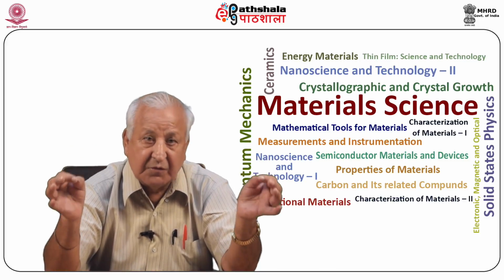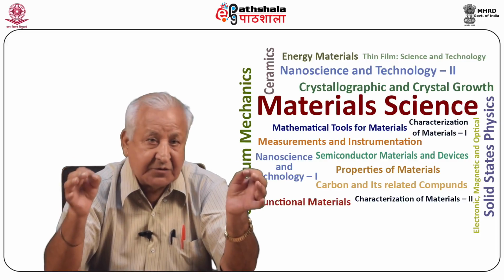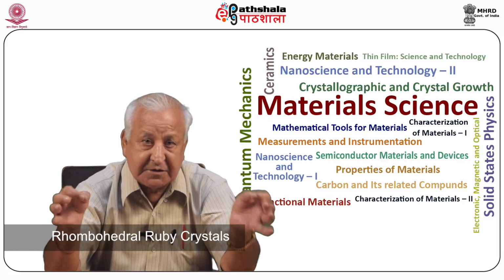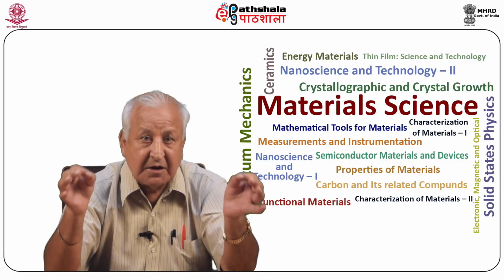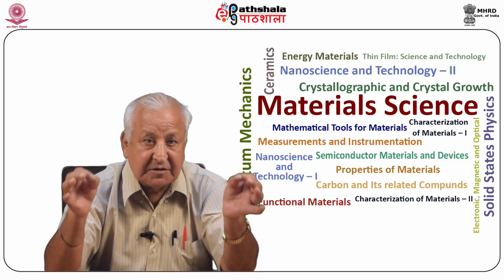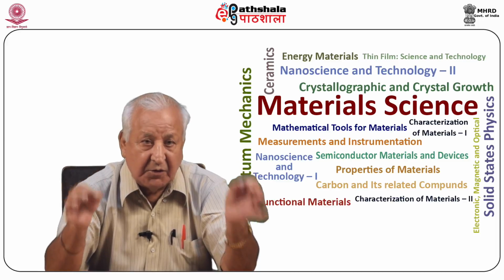The flux is removed from the grown crystals by dissolving the former in nitric acid, which neither affects rubies nor the crucible. Rhombohedral ruby crystals having size 1/4 inch across and large flat ruby plates up to 1/10 inch thick and several inches across have been obtained using this experimental setup at the Bell Laboratories, USA.